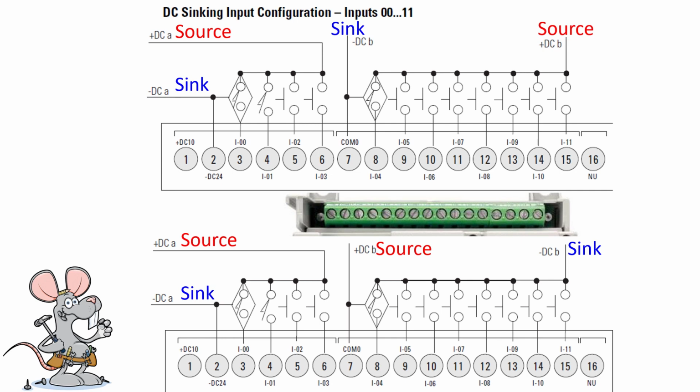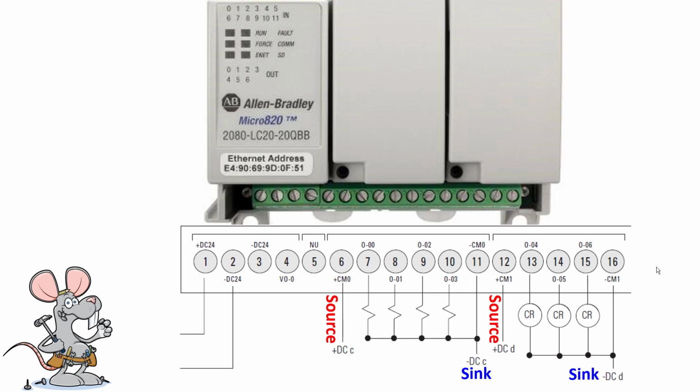On the bottom side, you see that it can support either. Notice that they have plus DC hooked up to common 0, and they're feeding all the sensors with the minus side of the power supply. The method of doing that is really outside the scope, but basically the opto isolator has 2 LEDs instead of 1. For the outputs, you have a variety of choices.